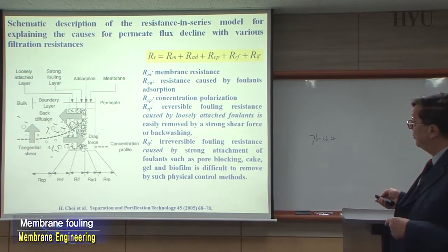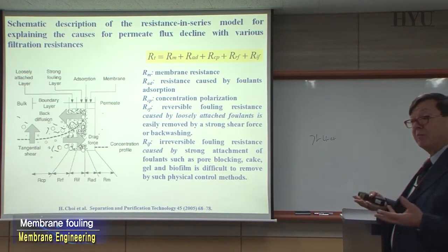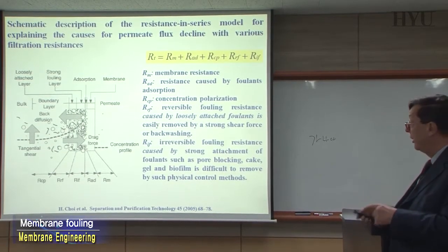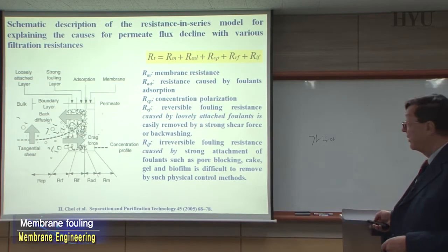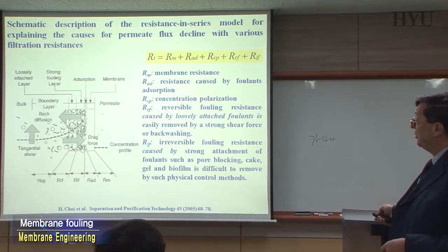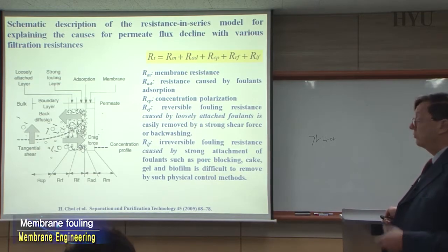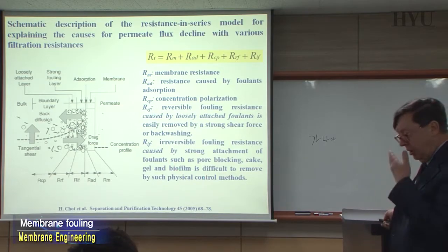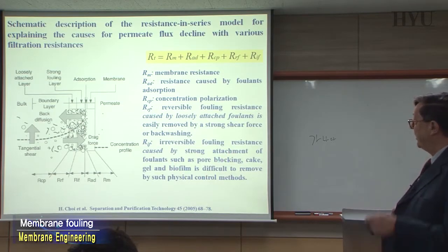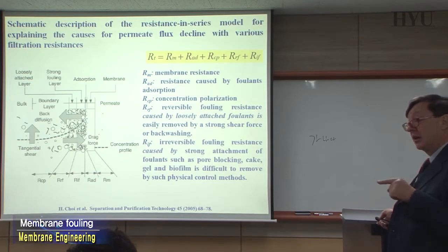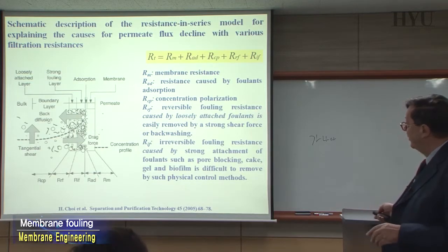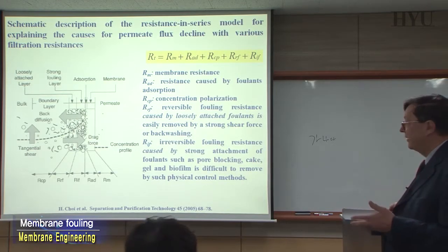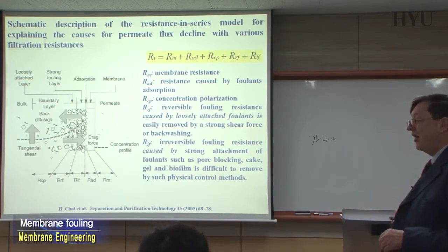It's very important when you do these kinds of things to know a lot about membrane morphology, because whether the membrane has large pores or thin pores can have an effect on the prediction and the control of this kind of phenomena. And there is another term, which is irreversible fouling, that is not easy to remove by changing the shear force, but is a strong interaction with the membrane, and you can have again everything that is related, not external but internal to the pore. Changing the shear force strongly and just stirring, etc., will have no effect on the pore blocking.